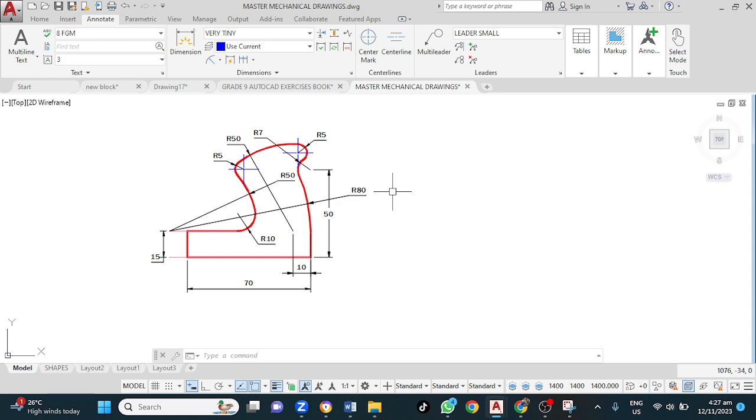In this video, I will be showing you how to apply circles and arcs to draw 2D shapes. The rules for blending lines and arcs are: one, always establish your centers first. You want to ensure that your centers are established first. Next tip, always draw what you know first and the rest will fall in place. Two important tips.